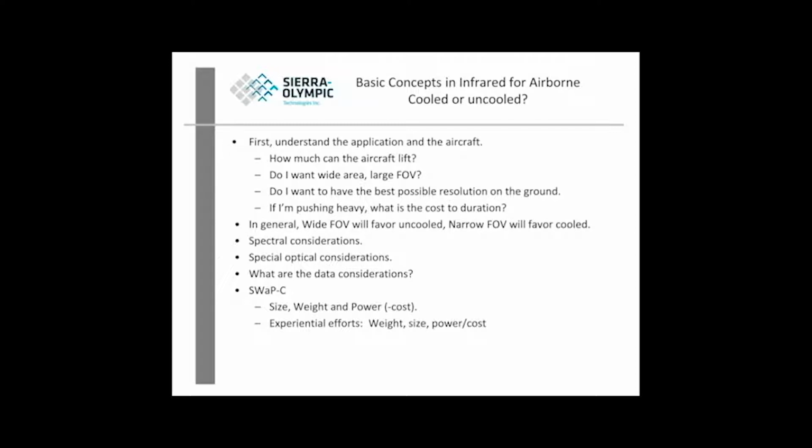Other issues are spectral considerations, what wavelengths do you want to look at? Optical considerations, do you need continuous zoom? Can you live with stepped field of view changes? And then data considerations will always come into play. What is the format of the video you need to generate off an infrared system? How many wires will the infrared imaging system require to transmit data? That's an important consideration. And then I use SWaP-C very